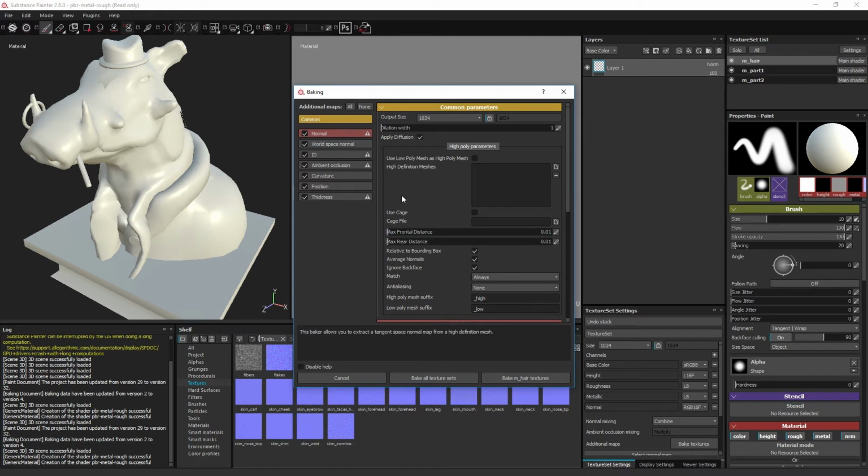In the panel to the left, you will see some buttons which each represents a single texture type, with additional checkboxes within them. The checkboxes let you decide individually between the texture types whether they will be baked or not, and the two buttons on top let you quickly enable and disable all the texture types. Moving to the bottom, you can close the baking window, bake all the texture sets with the current setting, or just bake the selected texture set with the current setting.